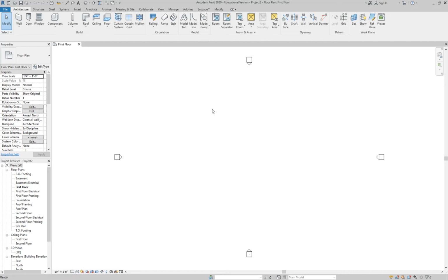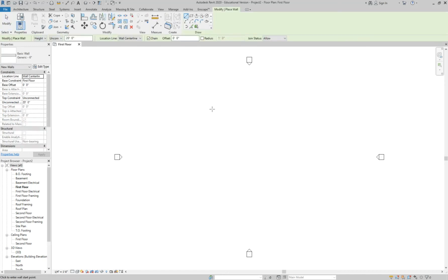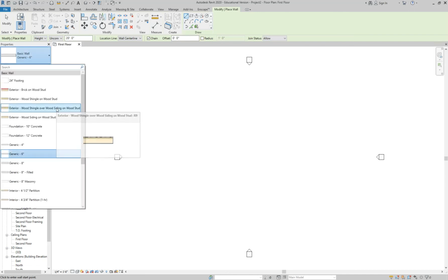Yeah, good. So look at the walls, and I mean, we've been using Revit for a total of 13 minutes and 40 seconds. Welcome everybody, you're doing a great job. Do you notice any differences? The wall is now 6 inches default. Before it was an 8 inch. Yeah, so even just the basic wall type, the generic 6-inch, it starts off a little bit differently. Do we see CMU? It was primarily CMU on the architectural side because it's a commercial project. So this template has different walls built that apply to residential projects.